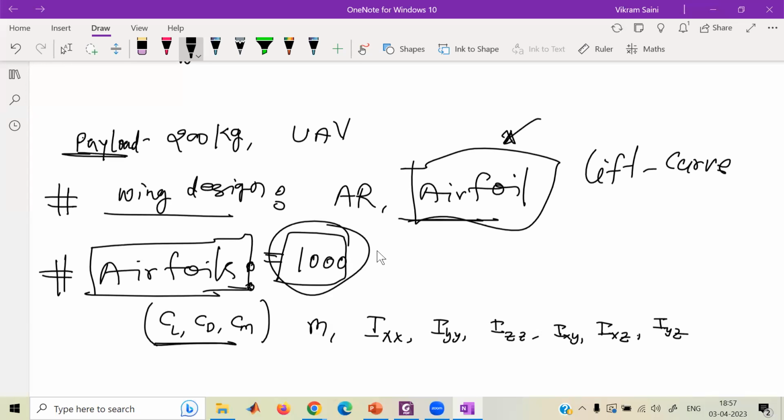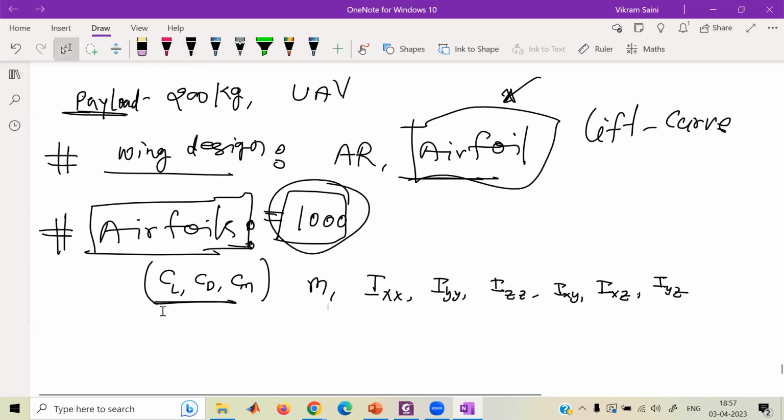Okay, so the aerodynamics group will give me CL, CD, CM. There are other quantities when you study dynamics. You just study the static stability, but when you study the dynamic stability, you will find out that CM depends on pitch rate. CM depends on angle of attack.